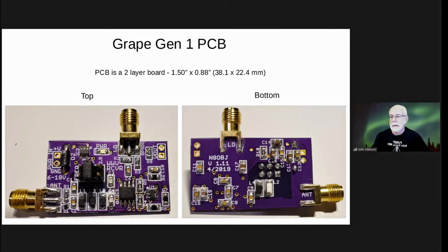It goes through the capacitive coupling. This is the mixer. And coming right down here, this is where the Leo Bodnar plugs in. We do the division, and this path goes straight into the mixer pin, so you can see it's nice and short, so it doesn't radiate too much. And you'll notice on the layout that this is all ground covered, and this is open such that the LC filter does not have issues with resonances of capacitive coupling to the ground plane.